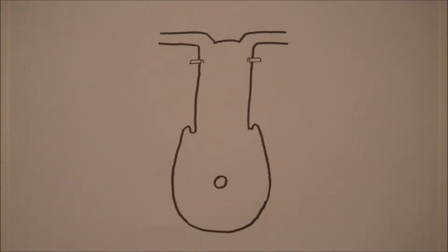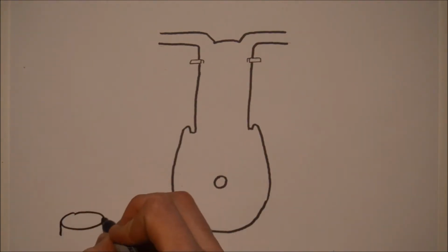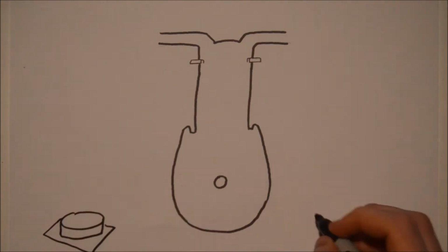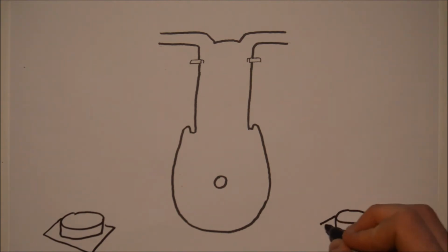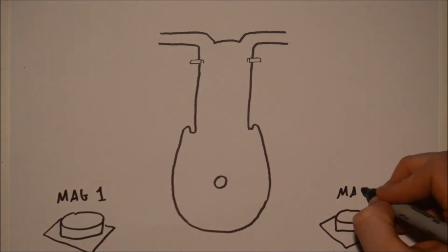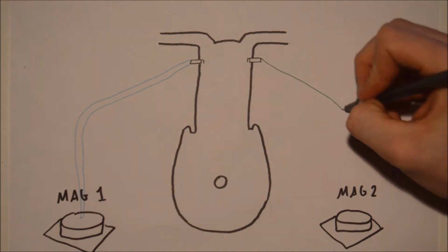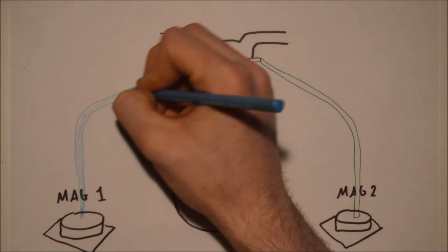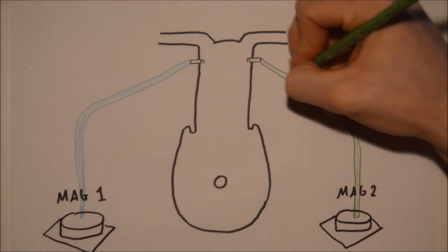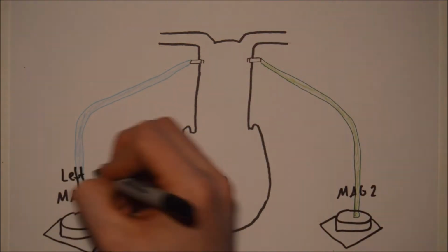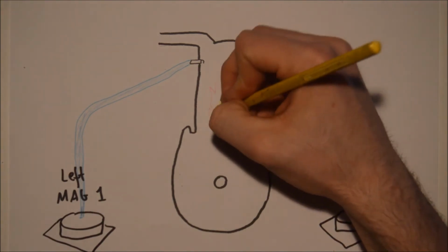Magnetos are used as they can generate their own electrical energy, thus keeping the ignition independent of the rest of the electrical systems. Thus, the engine continues running in the event of an alternator or battery failure. Most aircraft contain a dual ignition system, with each spark plug having its own magneto. This increases reliability should one fail and improves combustion and power output.